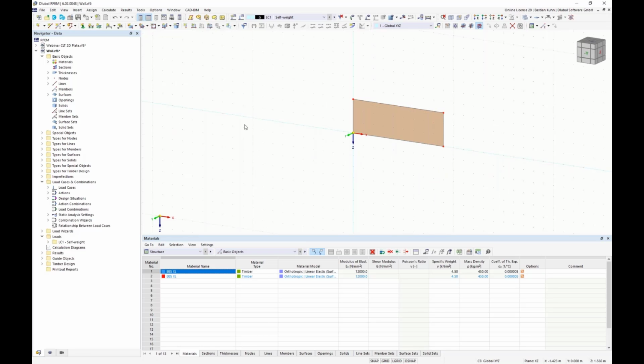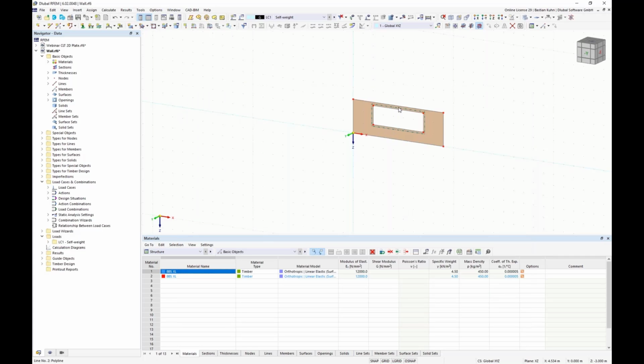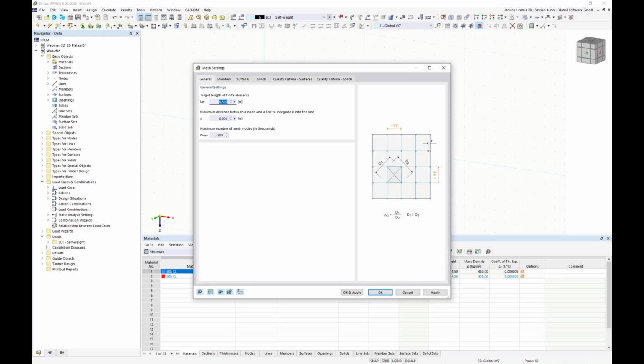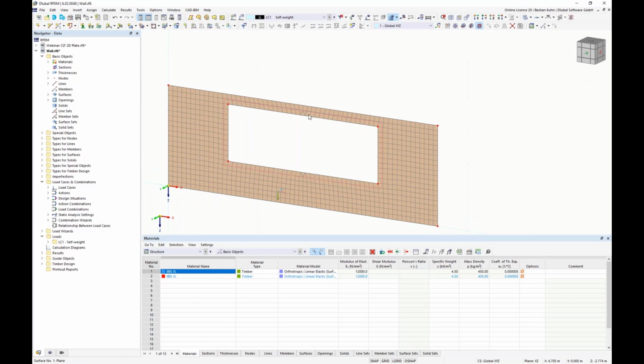So okay, we make it a wall, give it a little opening, assigned here by this, just to have it symmetric. Oops. And in order to see something with the shear problematic, because that's the only reason I'm showing you this example here, we make it quite narrow here on the top. And because it is this kind of narrow, I have to refine my FE mesh in order to have at least 2 elements over the height of this little spandrel in here.